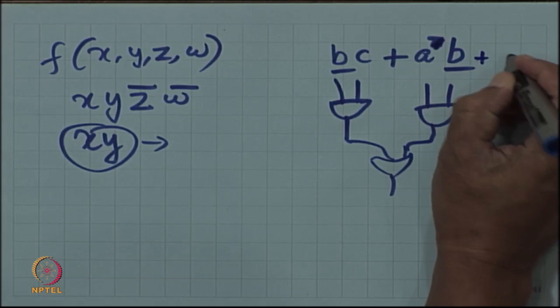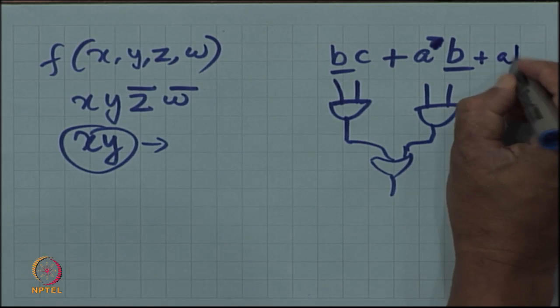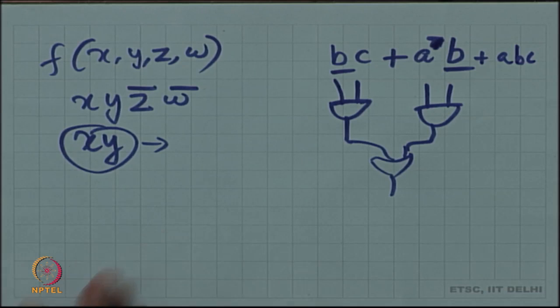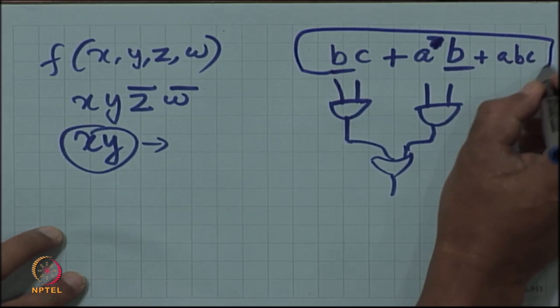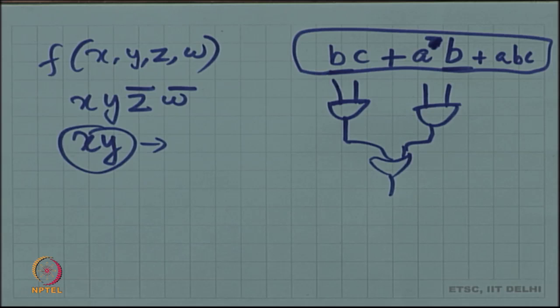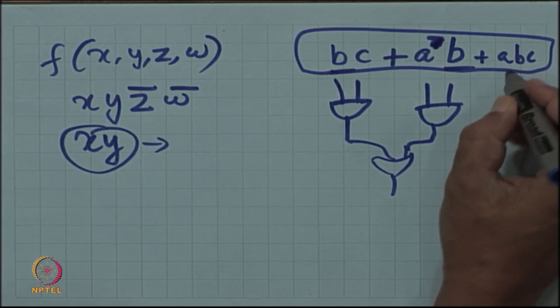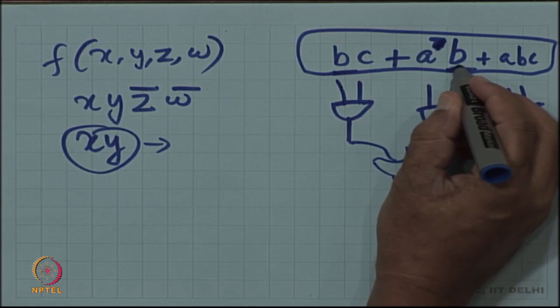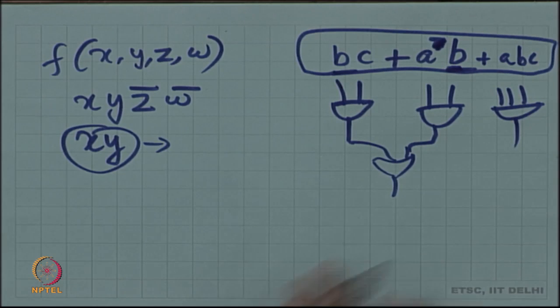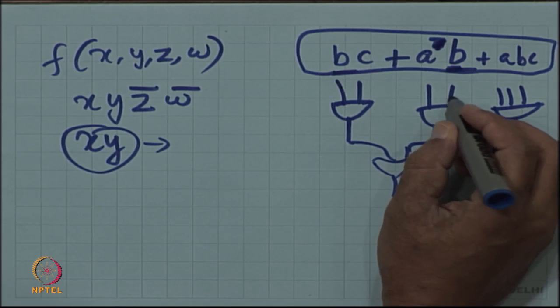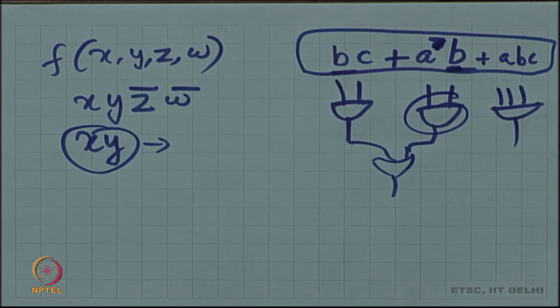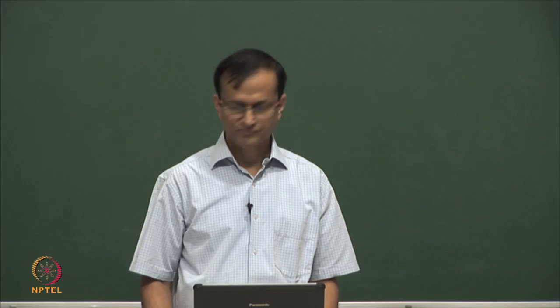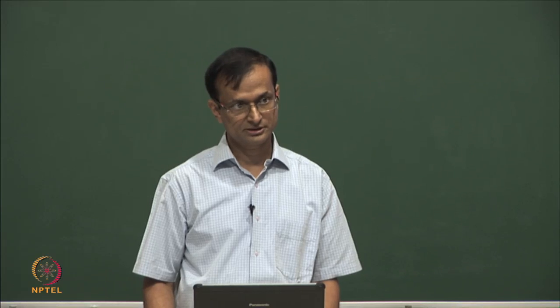If you had another one, if you had plus ABC here, that you can separately optimize, it is a different matter. Let us say this is my ultimate expression and I want to translate that in a straightforward way later on into gates, then that ABC here indeed translates to a separate gate structure. So, we are saying that every time such a literal occurs, that translates in some ways to an additional 2 input gate or whatever our minimum element is. Therefore, we count all of those occurrences.